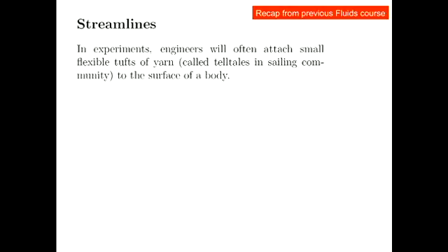I mean, if I'm working on this MUR motorsports problem, and I want to know what the flow around that car is doing, if I knew the streamline pattern, I'd have a good sense for what that flow was doing around the car, okay? So engineers often try to visualize streamlines. We stick tufts of yarn or tufts of wool onto the body that we're interested in, and they're going to align themselves with the flow direction, okay? And it gives us a way of visualizing what would otherwise be an invisible flow, okay?